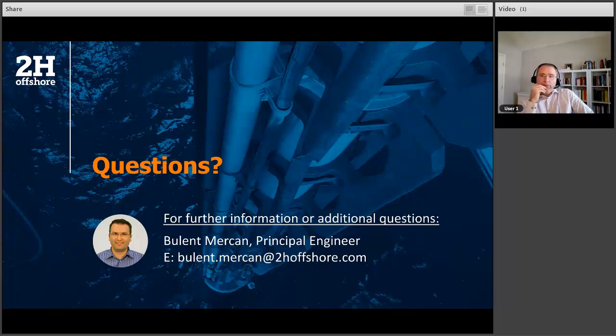If you have any questions, you can just reach out and email me and I can give you more information on that. The thing is, of course it depends on the insulation. These are magnetically attached. But if you have insulation on the riser, then we need to use special subsea clamps, and they are also ROV deployable. You install the ROV deployable clamps, and then you attach your sensors on this clamp, and we do this a lot.